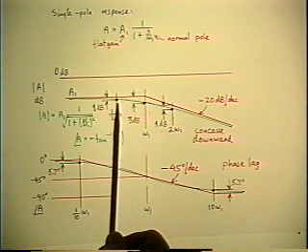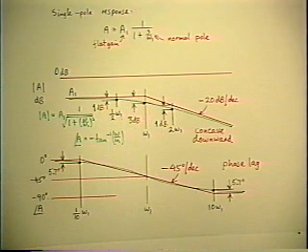That's the reason for identifying another point, the 1 dB down point. Now, the choice of 1 dB, of course, is arbitrary, because the curve only approaches the asymptotes at 0 and infinite frequency. So you have to make an arbitrary choice of when you say the curve has approached the asymptote sufficiently closely that you can say it got there.